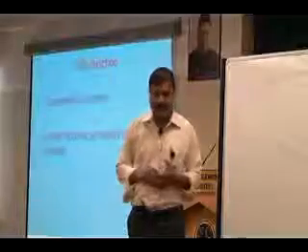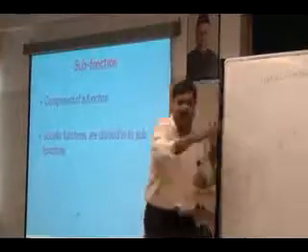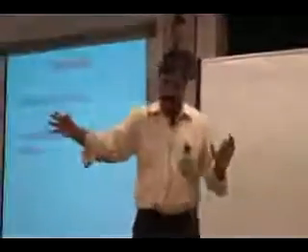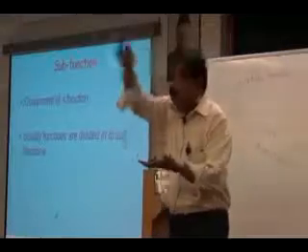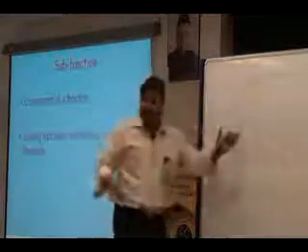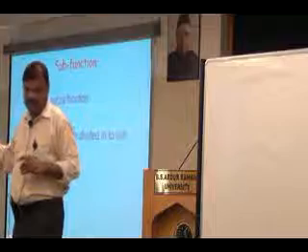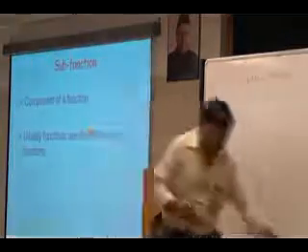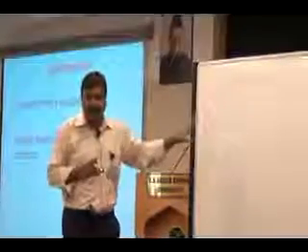If you don't have that arrangement, your vehicle will keep on oscillating, your seat will keep on oscillating, because the spring has absorbed the energy. The spring will dampen on its own, but before that, you will experience a lot of inconvenience. You will be thrown up and down if your dashpot is not working. So the functionality to be achieved is energy absorption and dissipation, and how that is achieved is by means of a spring and a dashpot.